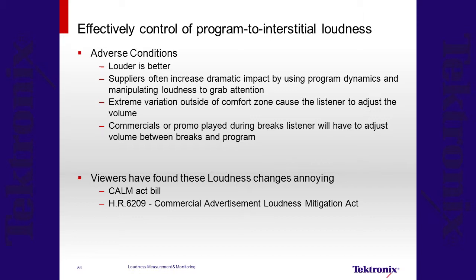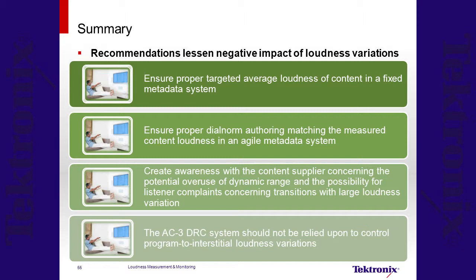To summarize these recommendations, the purpose of the ATSC Recommended Practice A85 is to lessen the negative impact loudness variations can have in the listening environment. In order to achieve this, it's important to ensure that the target average loudness is maintained when a fixed metadata system is used, and suitable measurement equipment should be used to monitor the loudness of the audio program. In the case of an agile system, the dialnorm should match the measured loudness content.